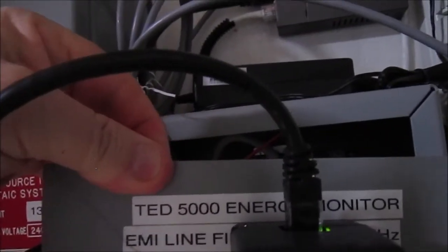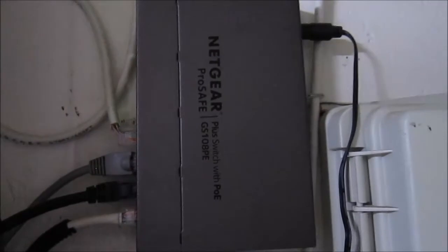They're powered up from the right hand side of this TDK line filter. I have 240 volts coming in. It filters and isolates the Insteon system to the left hand side. On the right hand side, we're taking a power tap off there, energizing the measuring transmitting units, and also energizing this receptacle that runs the TED transmitting device, and the communication signal is transmitted via the RJ45 up to the switch, and that's how we're viewing it on the web page.